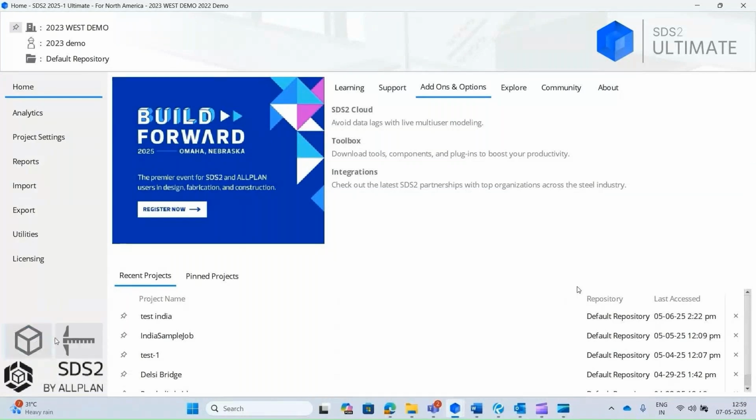But for example, if you're working in a modeling tool, all the modeling related features will be activated. Drafting will work as a viewer. You can view the drawings, you can navigate through. You can open a report, connection calculation, or any kind of report, but you cannot edit anything. Similarly, if you have a drafting window, modeling will work as a viewer. You can view the model, you can navigate through, you can add notes, but you can only use the full capabilities of the drafting license.